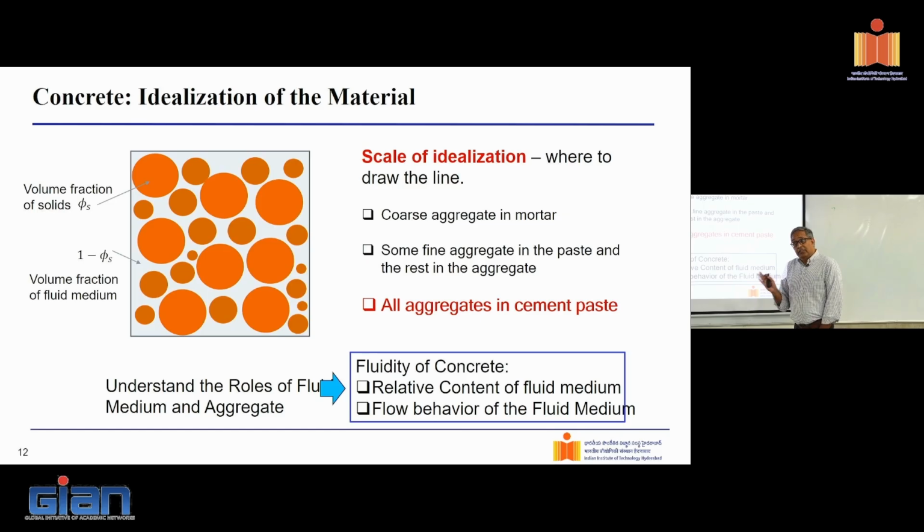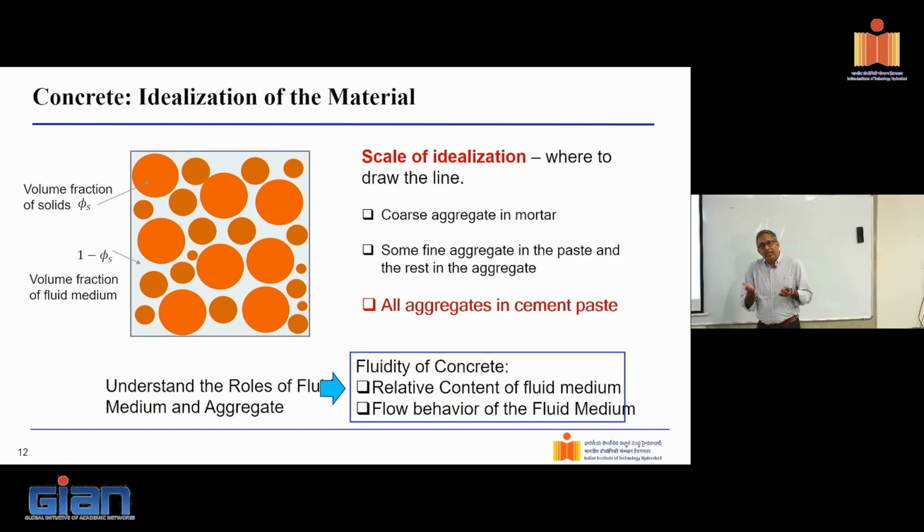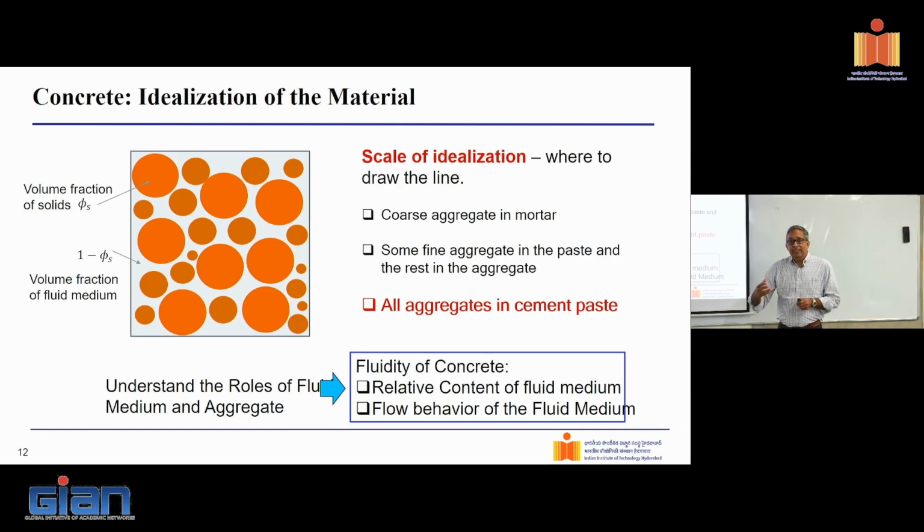Now, this is also done. One place where this is done is when we do SCC, self-compacting concrete. Those of you who've done self-compacting concrete know that we pack it with fines. What happens then? We actually take the fines and count them towards a fluid. Although they are aggregate, we count them towards a fluid, and the fluid behavior of that fluid medium, which is now paste and some fines, becomes important in controlling the flow behavior of concrete.